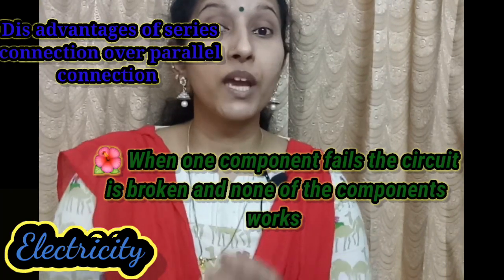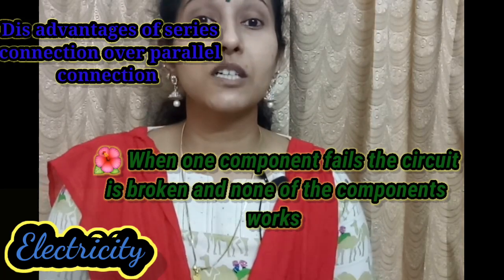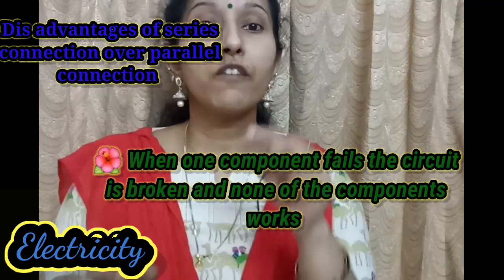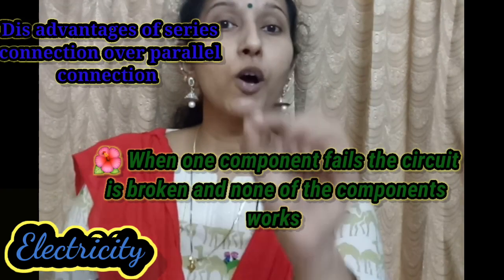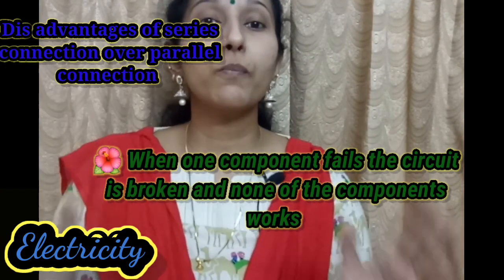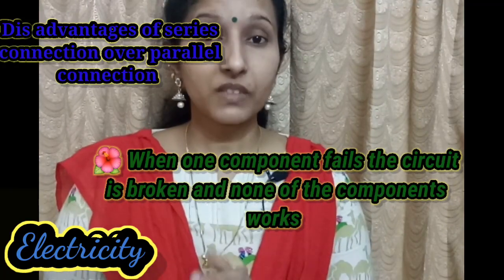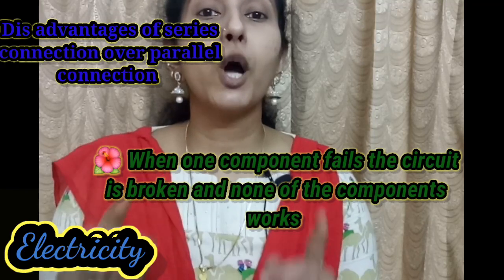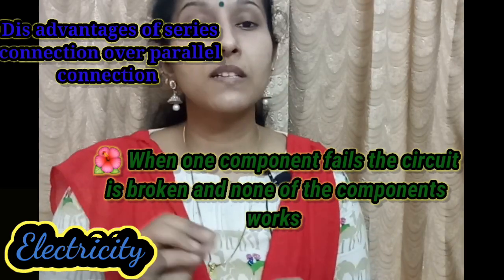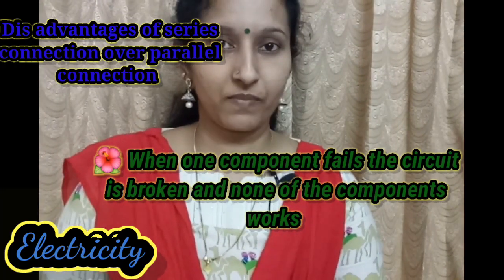Also you may see that the electrician spends a lot of time locating the trouble, because it is very difficult to find out, since any small problem in any component in a series connection affects the entire circuit. So the entire circuit breaks and none of the components works. So that is the second drawback. If one of the components fails or there is any small problem in one component, the circuit breaks and none of the components works.